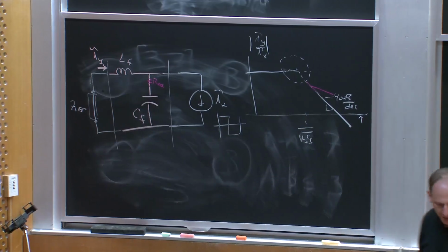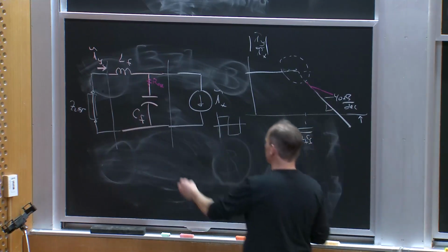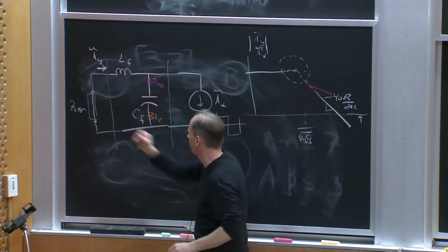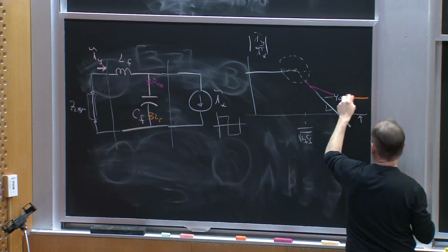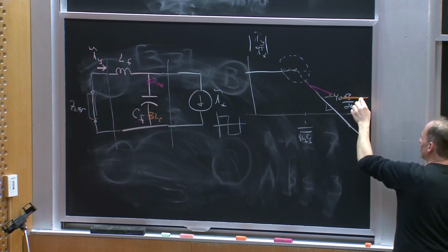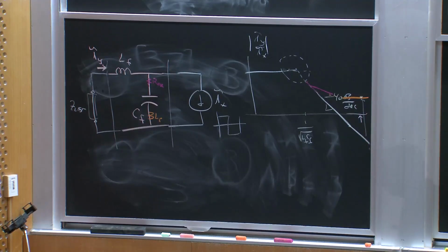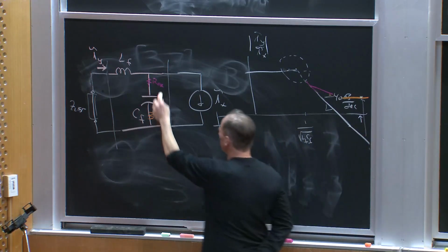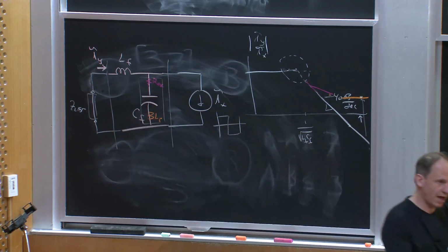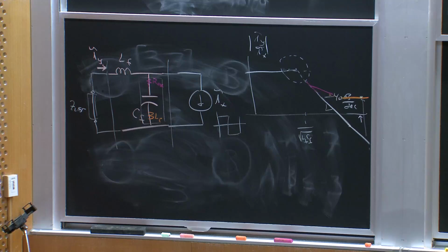And then if I keep going up and I have some parasitic inductance here, L parasitic, then I just have a current divider between LF and LP, and in fact, this might even flatten out, right? So I might be thinking I'm going to be way down here, but really my attenuation is up here, and I don't get nearly as good a performance as I hoped. So this could be due to internal component parasitics, okay? Or it could be due to layout parasitics, how I place everything on the circuit board. Parasitic inductance and resistance is one thing I worry about. Parasitic capacitance is another thing I worry about, okay?